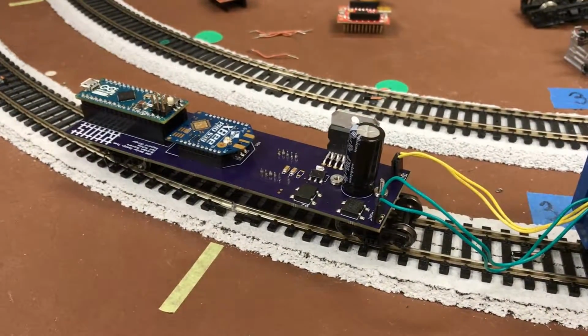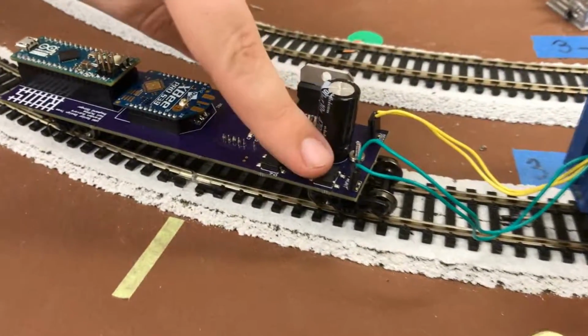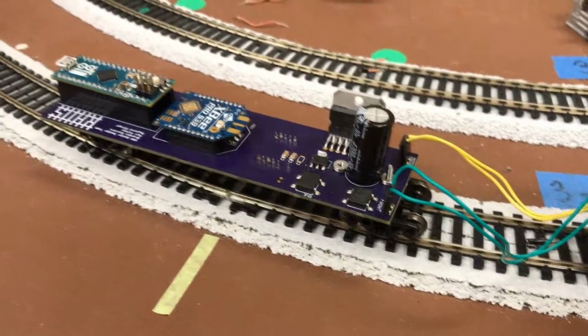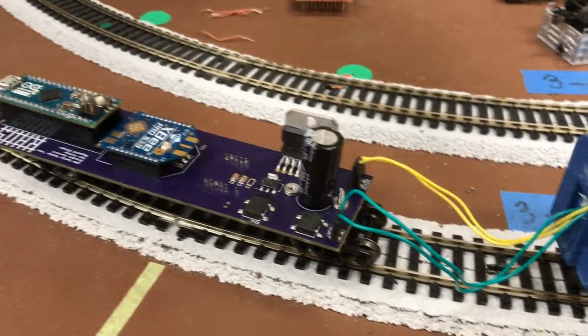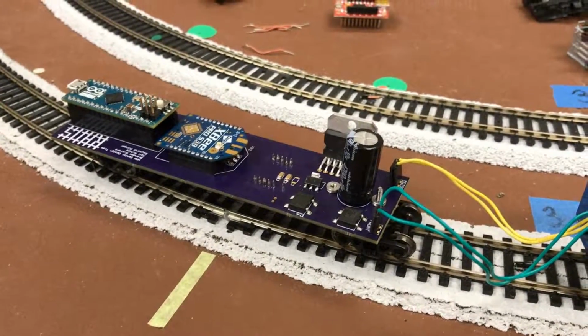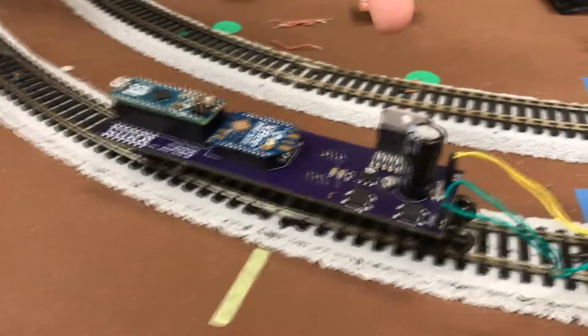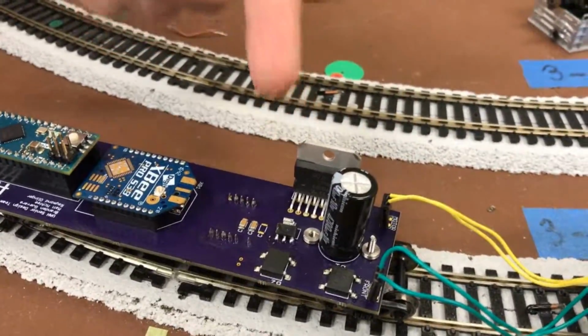First, here is our rectifier circuit. We have wires coming from the wheels that are connected to the inputs of each bridge rectifier. We then have this capacitor to smooth out the rectified signal from the bridge rectifier to get clean DC power. We then use this power to operate the Arduino, the XBee radio, and the L298N motor driver directly.